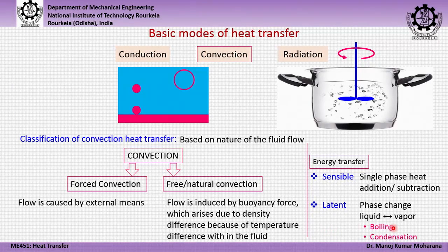whereas the reverse process, converting a vapor into liquid, is called your condensation process. For the condensation to take place, the vapor should come in contact with a solid surface whose temperature is less than the saturation temperature for this vapor or the liquid.